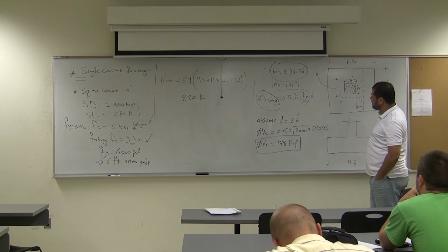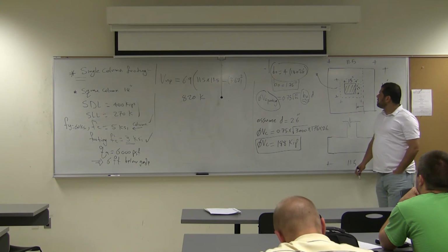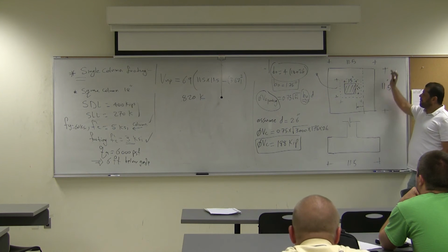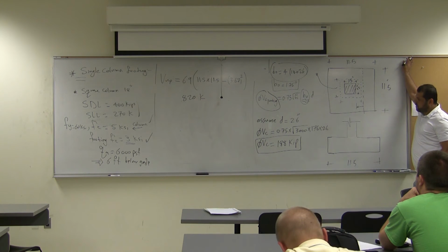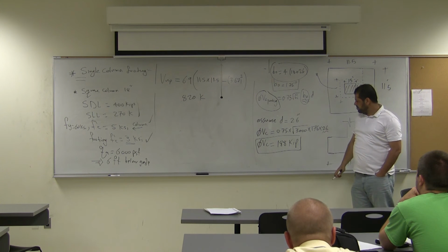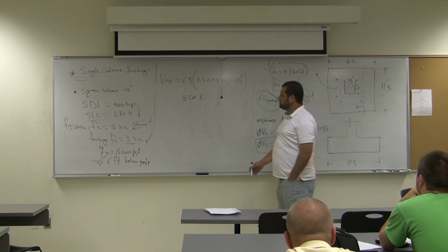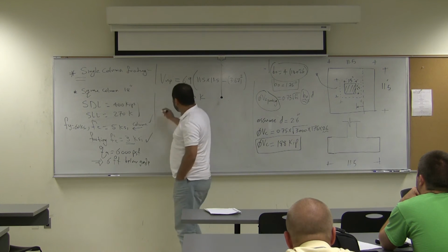So VU ultimate is way, way greater than VC. I'm redoing the VC. Oops, I switched. Do you multiply by the 26 in here? Yes, that's 188, and this is 820. So we need a much, much bigger footing. That's what we see in here.